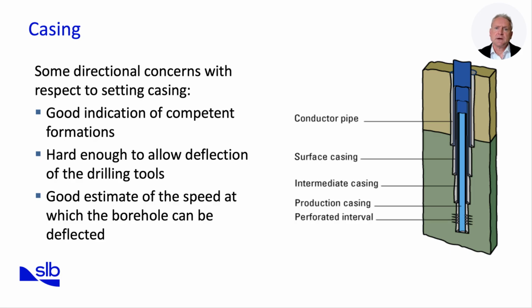After casing is run, it is cemented in place. Cementing provides zonal isolation, preventing fluid migration between formations and protecting aquifers. It also secures the casing, ensuring structural integrity. Once cemented, the casing allows higher mud weights, enabling safe progression of the well. In summary, casing is not simply a mechanical support, it is a design element that governs mud weight management, enables deviation, provides zonal isolation, and ensures the safe continuation of directional drilling.